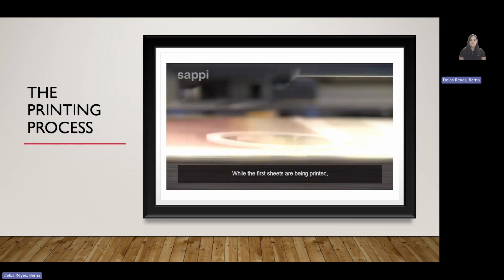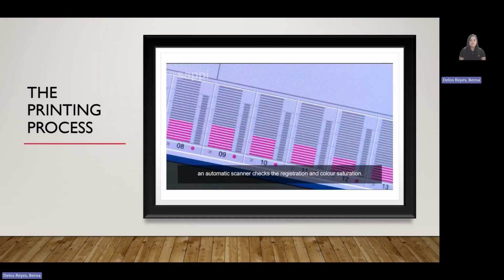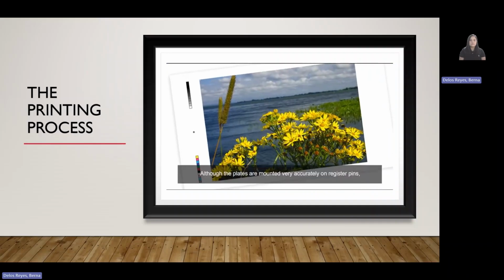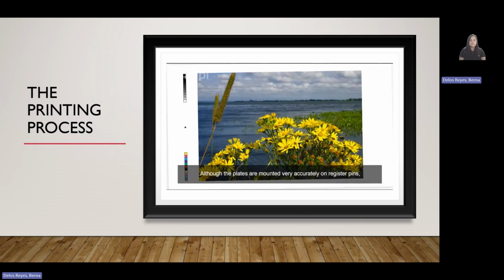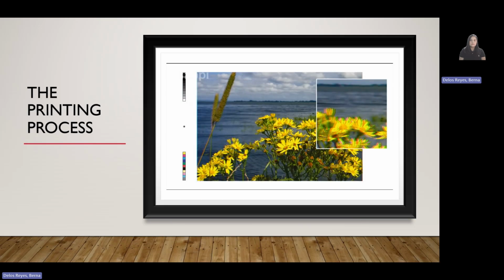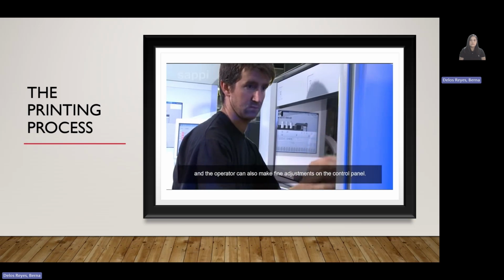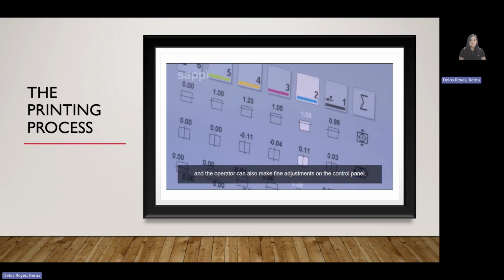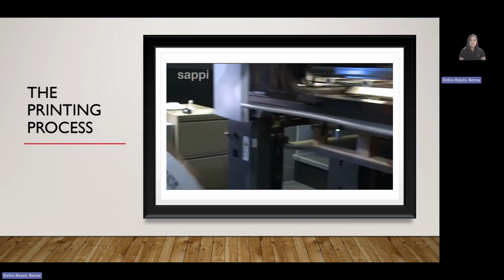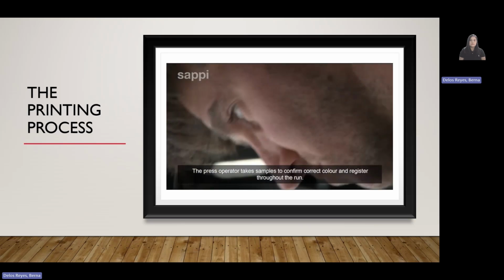While the first sheets are being printed, an automatic scanner checks the registration and colour saturation. Although the plates are mounted very accurately on register pins, they may still need fine adjustment to be perfectly aligned. The press automatically corrects this, and the operator can also make fine adjustments on the control panel. The press operator takes samples to confirm correct colour and register throughout the run.